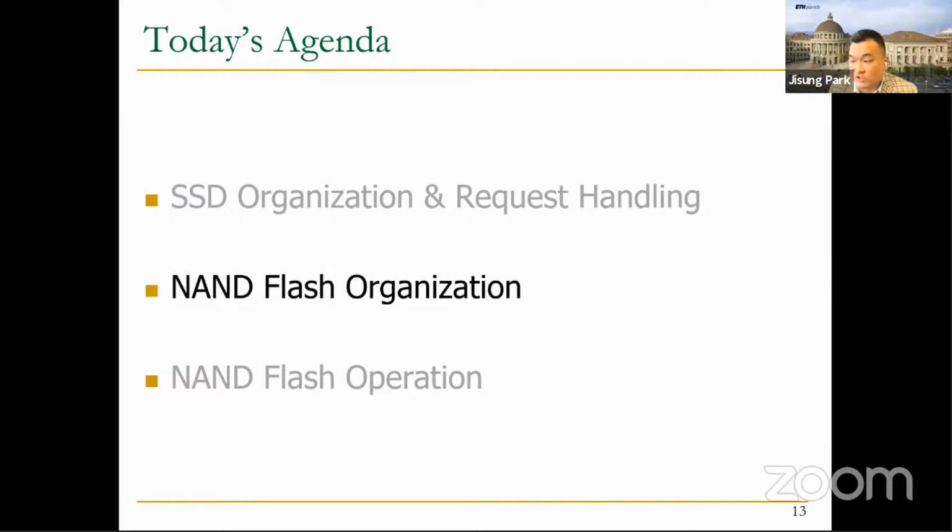Yeah, it is a very good question. Actually, the parity data is stored into the NAND flash memory along with the raw data, the requested data, so that whenever we access the stored data, the parity values would also be read together and used for ECC decoding.